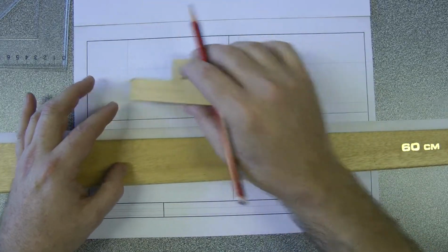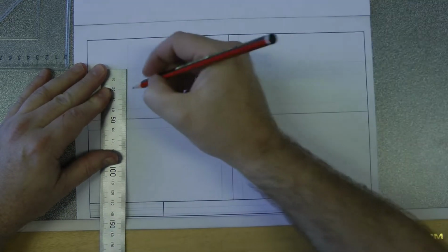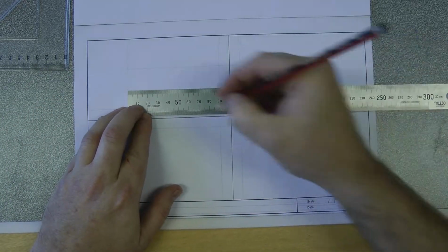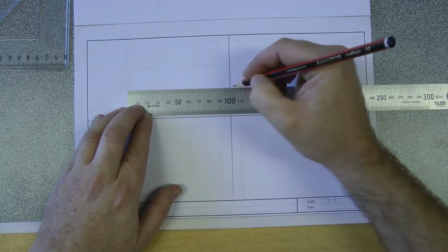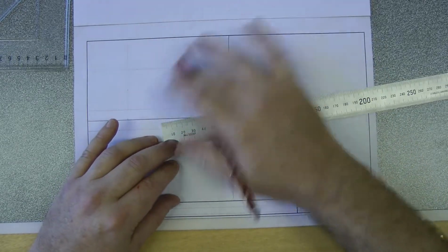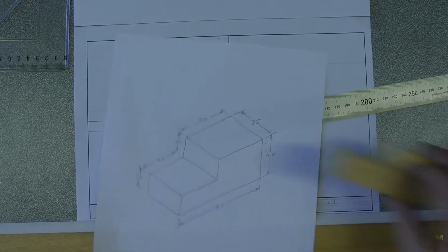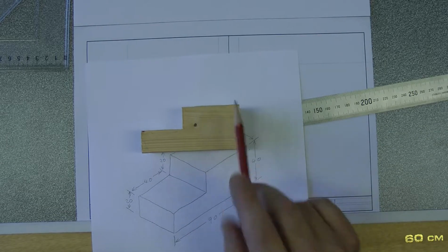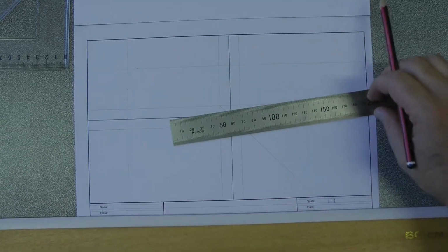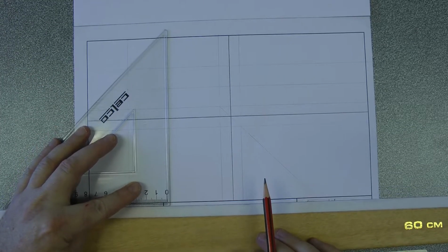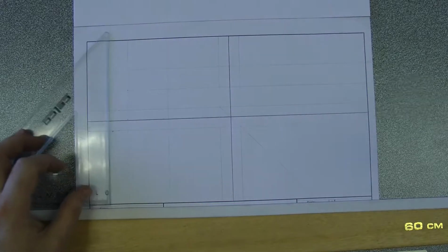Now what I've got to do is this corner cutout. So I'm going to measure from here, I'm going to measure down 20, because that's how far down I said, and I'm going to measure from this side 40. So I'm going to measure 40 from here. I could equally measure 50 in from this direction here, because that's my dimensions. I've got 40 on this surface and 50 on this one. So that one there is 40, this one here is 50. So now I have a horizontal line going through there, that's my 20, and I have a vertical line going through there, both construction lines.